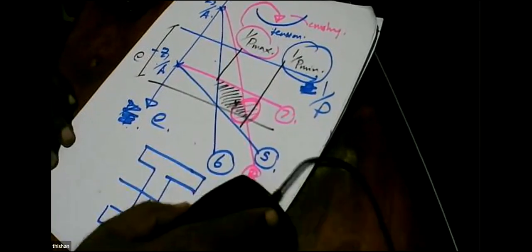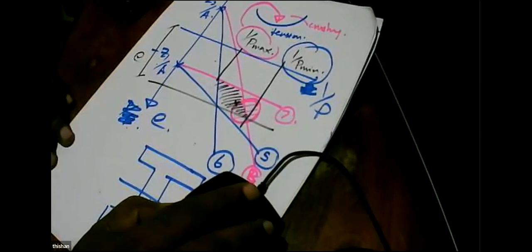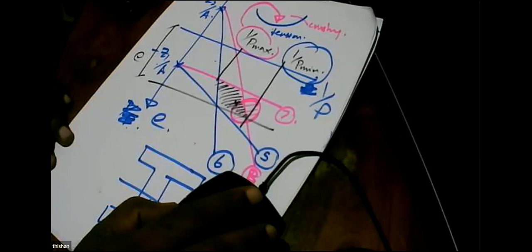Will there be any changes in the equations between post-tension and pre-tension? How to avoid the sagging moment effects near the supports in post-tension? Post-tension and pre-tension equations are the same. But what differs is the loss calculation method.